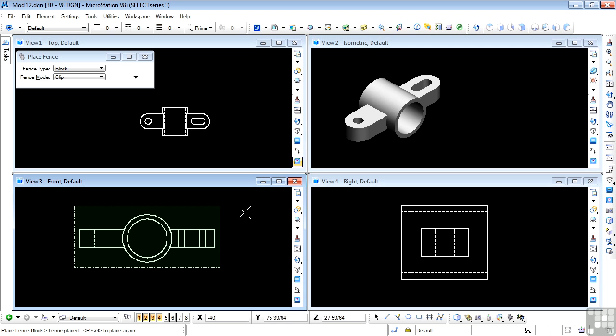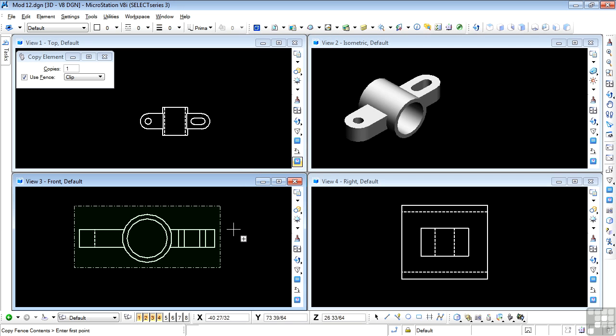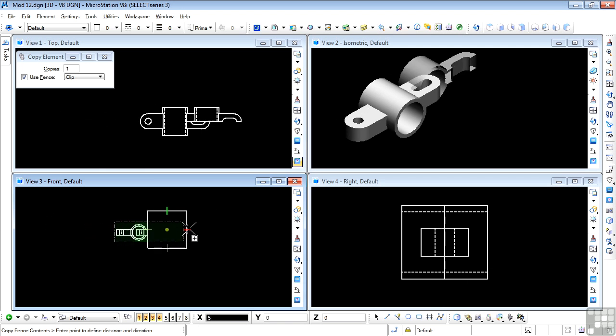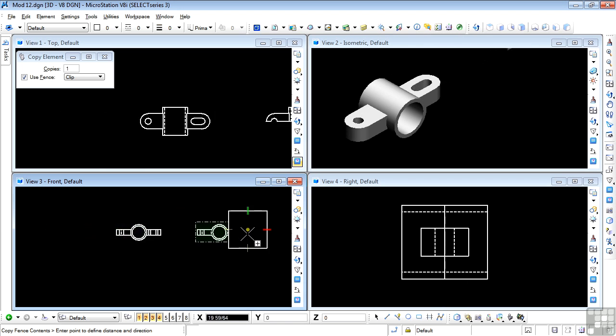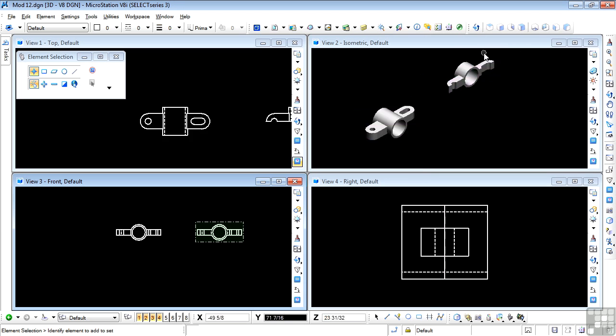So I'm going to right click. And what I'm copying is the portion of the bushing between the front and back clipping planes. I'm going to left click. I'm going to zoom out a little bit, drag this over a little bit, flop it in place, right click. And here we see my section. That's a vertical section. It's the back half of that bushing.